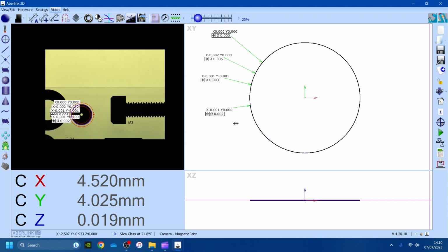And what we're looking for basically, is for the true position to be less than 10 microns and any given axis position to be less than sort of 5 microns. As you can see, this is the case on the screen here. So we have verified that the Z rotation is all good. And we can now actually start measuring with the camera.